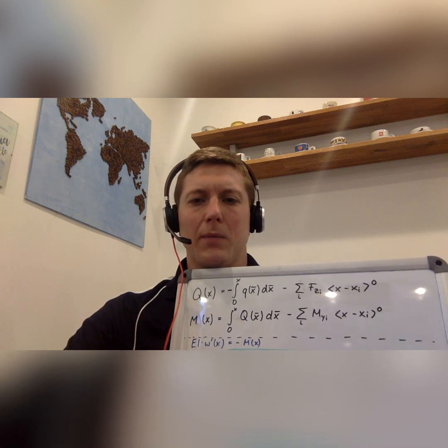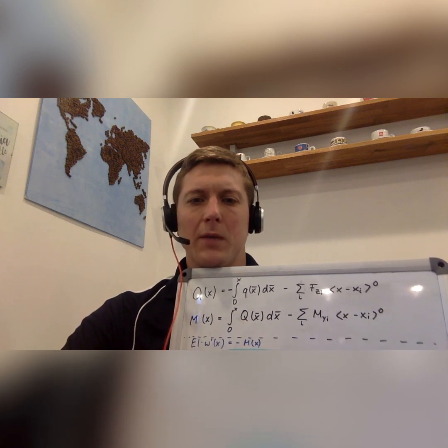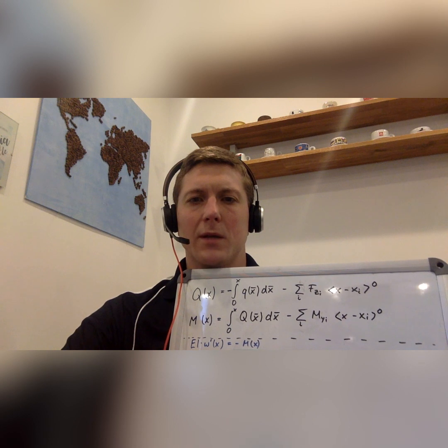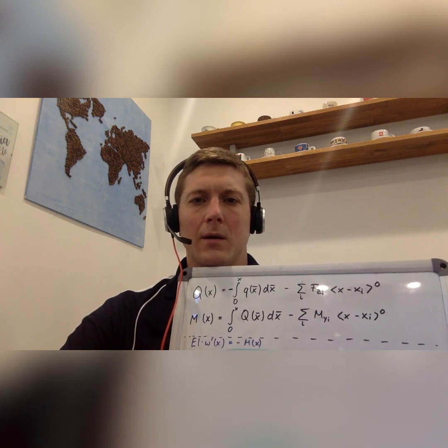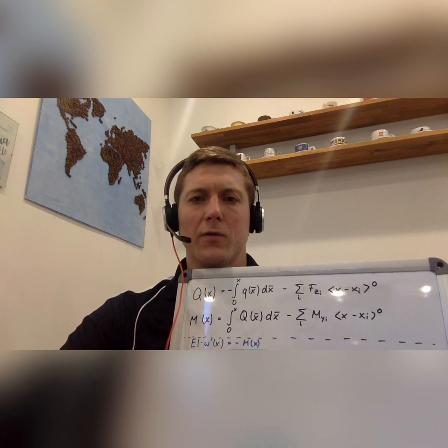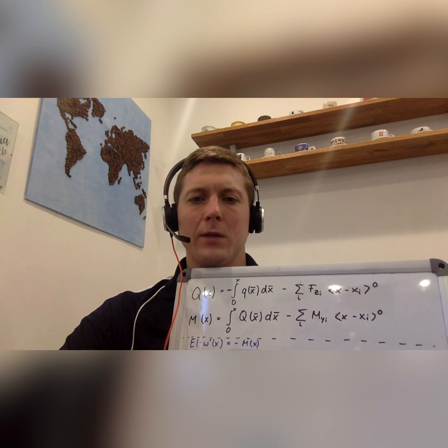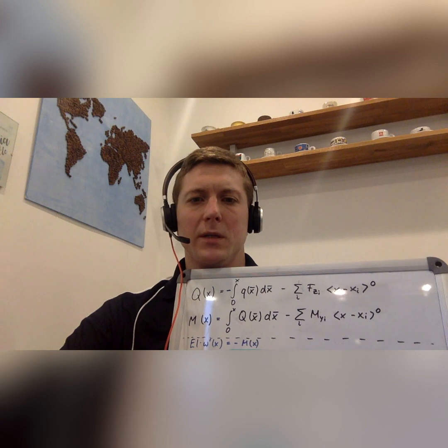There is only a planar beam and only moments with respect to the y-axis. And as already mentioned, this equation is just a model assumption that there is a linear behavior between the deviation of our beam and the bending moment. And using this equation, we can solve for the deviation or for the curve, so for the change of the position, this w, because we simply have to integrate over the bending moment to get the derivative of the change of the position in z direction.